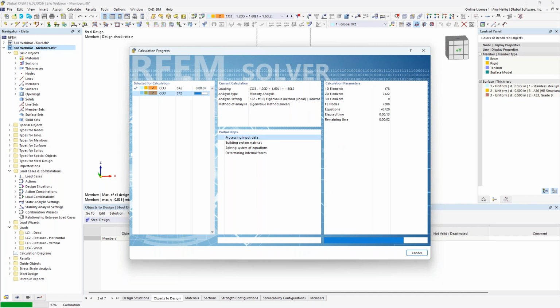So we have run the static analysis load combination shown here in line 1, but line 2 is running that eigenvalue analysis. It's going to import in all of the axial loads on the surfaces as well as the members. So you certainly want to choose a load combination that has the highest gravity loads, for example. And we're going to determine the 10 failure buckling modes of the structure along with the critical load factors. So this will just help us evaluate where we may potentially have issues with buckling with the structure.